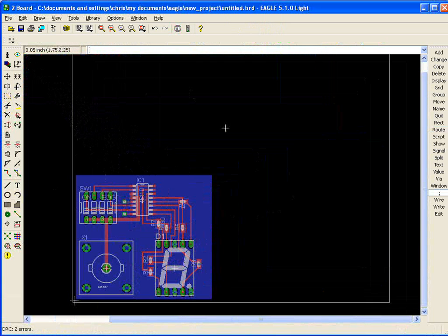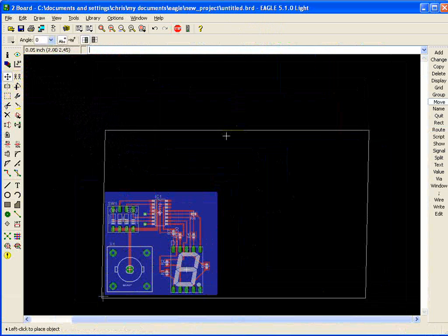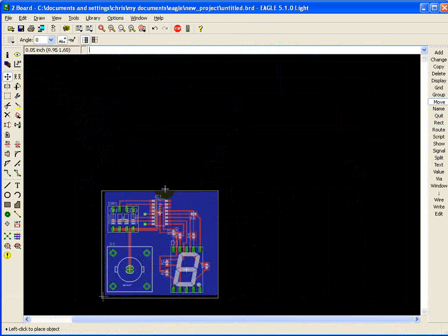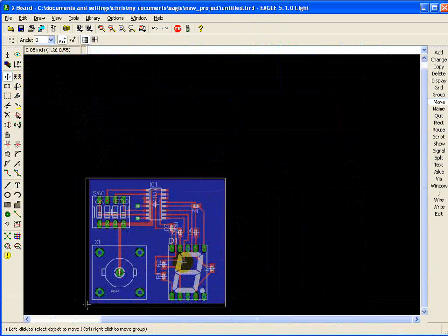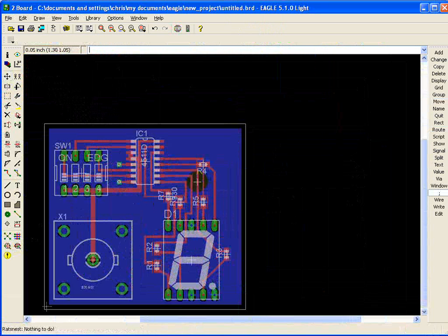So I'd have to go back and clear those up, make sure that the board house I'm going to has that drill size. If not, I need to change it and possibly move those vias out. Otherwise, I need to just bring this board in. Might be a little too far. And we're good. Hit rat's nest, it'll clean up your ground plane, and we're done.